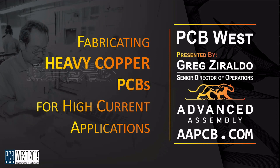What about custom reflow profiles? Advanced Assembly, I think you guys have some ovens that allow some targeted temperature measurement and very quick custom reflow generation. Can you tell us a little bit about how that works? At Advanced Assembly, we actually have two different capabilities of reflow. We have conventional reflow, which I refer to as basically your standard conveyorized pizza oven with a multitude of different heating zones and cooling zones for reflow.